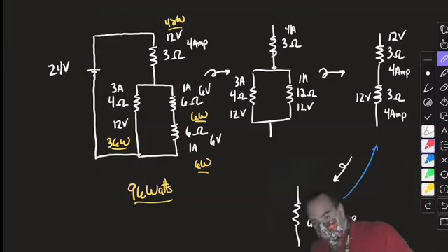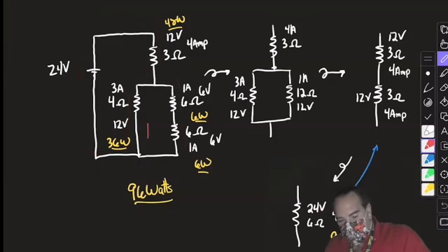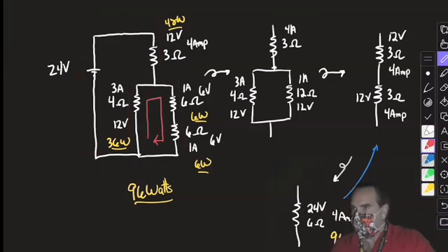On the other hand, Kirchhoff's rule should fit here too. Since the current is clearly going downwards through both of these, based on the direction of my battery, I have an increase in voltage on the left side of 12 volts and then 2 decreases of voltage of 6 volts each. The sum in that circle equals 0.